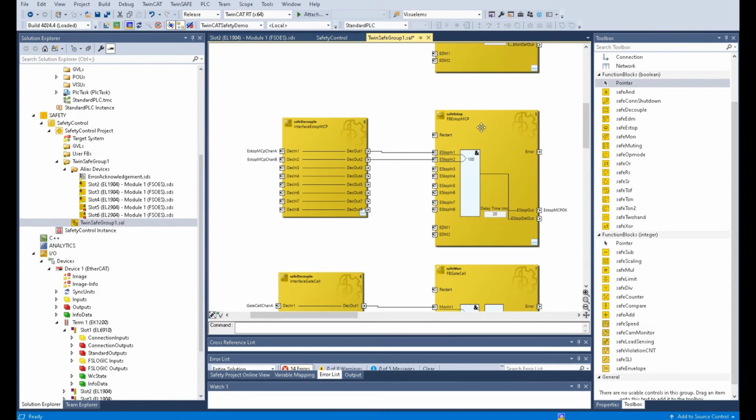For each function block which is used for connecting the safety input component, for this reset, we need to connect the reset signal to reset this function block after the physical channel signal recovers. From the application view, for different components, we need a different reset.